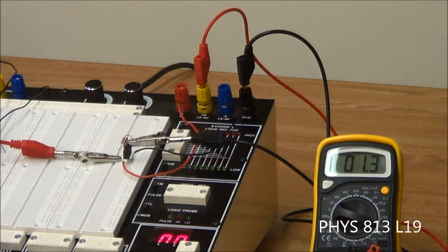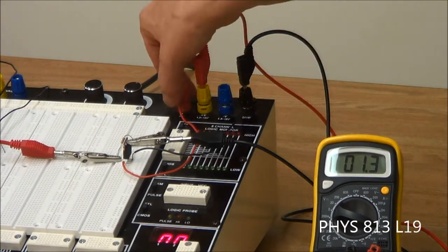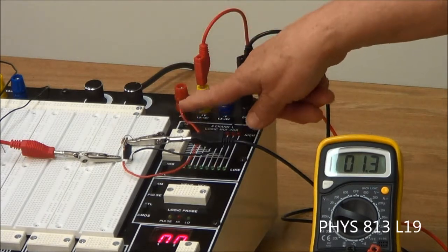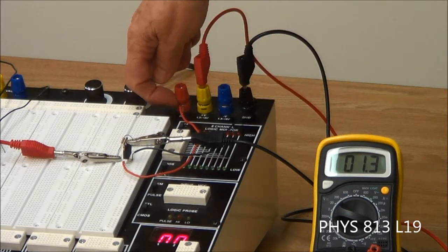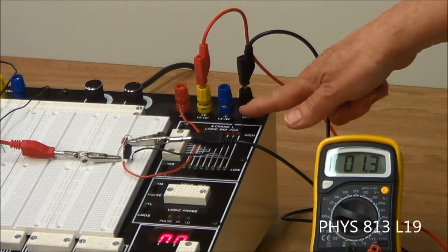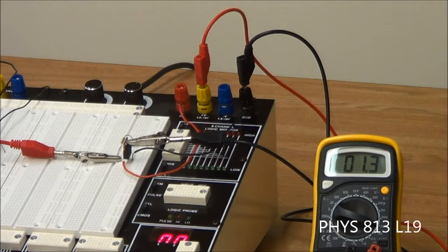One comment I wanted to make is when you're putting these wires in here, you want to make sure that the insulated part is not getting under there, because if you do, it will not make good contact and you'll wonder why things aren't working. And I found that out from experience. So it's always a good idea if you can still see just a little bit of the stripped part when you're putting those into there.